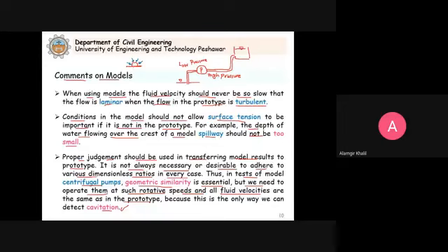And when it comes here, you see enormous impact will be developed here. And if this is the metal surface, then what will happen? It will put so much pressure here that it will eat the material from here. As a result, a very small cavity will be created here. And if this process continues, another small cavity will be created, and another, and you can see it will cause damage to the runner of the pump turbine, and also even if this occurs here. So that's why this cavitation is very dangerous.